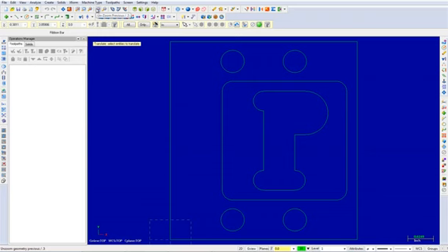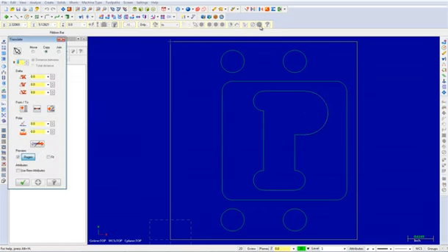Holding the Shift key, select the following rectangle. Now choose the End Selection button. The Translate dialog box will appear. In the Translate dialog box, enable Join and enter a delta Z value of -1.5.